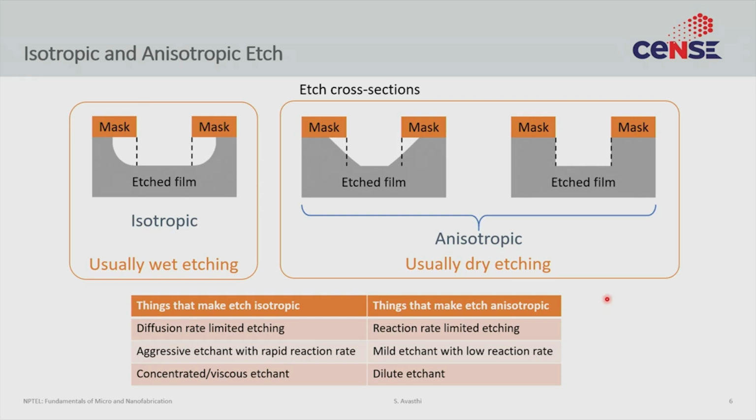Etching is essentially a deposition process in reverse, so I shall not go into excruciating detail like we did in CVD to completely understand the process. Very frankly speaking, the process is not as well understood, but the basics still apply. You can either be limited by the diffusion through the boundary layer or the stagnant layer of the etching solution, or the reaction could be limited by the surface reaction. Depending upon which of these is the limiting factor, the etches tend to be isotropic or anisotropic.